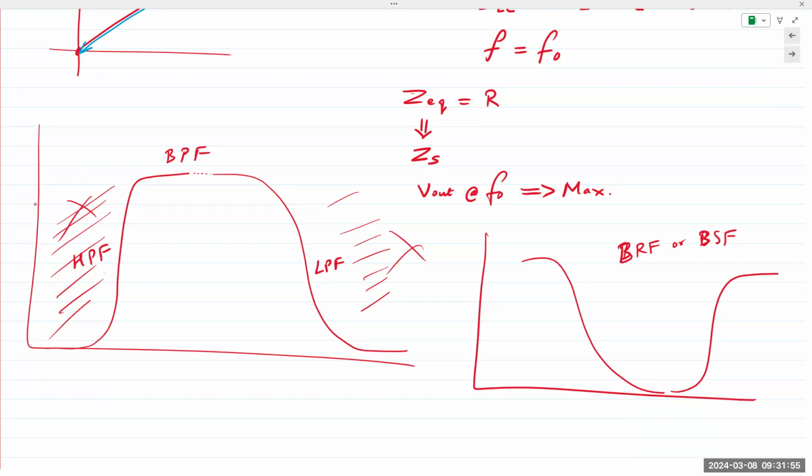This is particularly useful when we are trying to eliminate the signal noise from our power outlets. So power outlet signal is 60 Hertz. Sometimes it can cause interference. And so we use something known as a notch or a line filter. It filters out that particular signal frequency of like 60 Hertz. Okay, it's very, very narrow. It's a band stop, band reject filter.